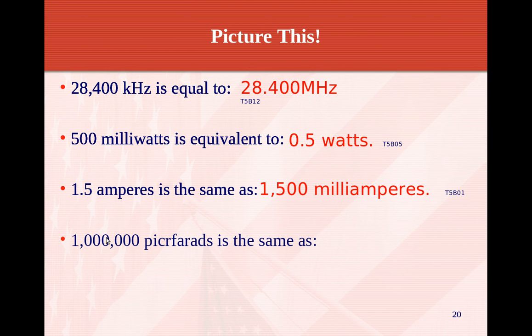Okay, 1 million picofarads is the same as 1 microfarad. So we're going from 10 to the minus 12 to 10 to the minus 6. So 1, 2, 3, 4, 5, 6. So it'd be 1,000 nanofarads, or 1 microfarad.